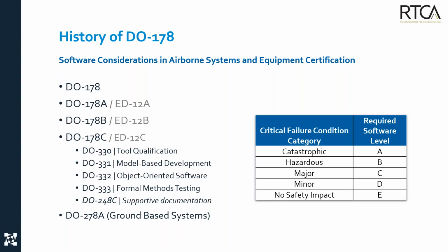The original DO-178 standard was released back in 1982. However, it was considered not very useful, then quickly followed by the revision DO-178A, published in 1985. The revision focused more on modern software engineering principles and verification practices, and introduced a correlation with critical failure conditions. So you'll have level numbers, 1, 2, and 3, with level 1 being the strictest. You may know it better as Development Assurance Level, or DAL.